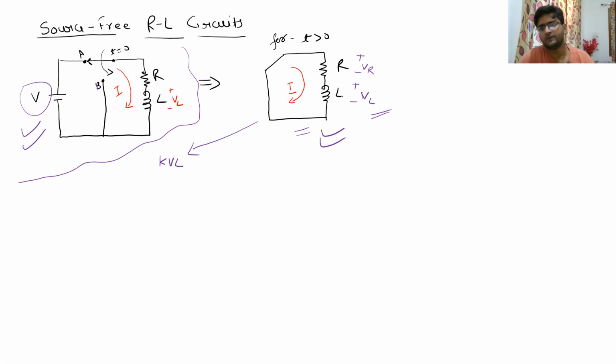As I told you previously, when this particular setup happens, the voltage across the inductor is reversed, right? So actually this inductor will be supplying current, so its polarity will be like this. But for simplicity, for the sake of the mathematical equations, I am just assuming that this voltage VL has a polarity like this, in a similar way as the VR. Anyway, it is going to come out negative, so we will not be bothering about it.